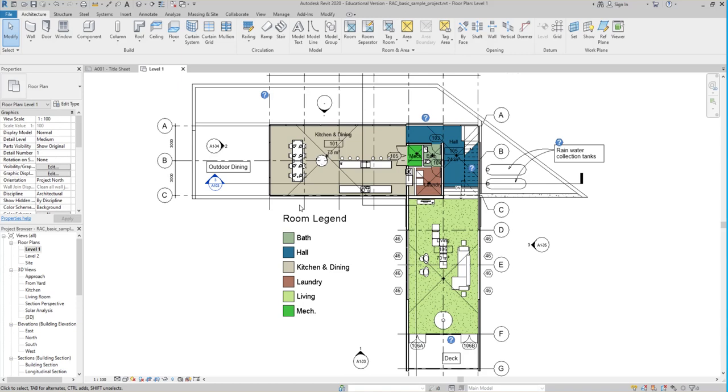If you're thinking in terms of engineering, line weights a lot of times, like if you're a mechanical engineer, and I mean that like nuts and bolts, right? You're doing product specification. Line weights are going to be associated with things like what you cut. So if you're working with a laser cutter, magenta means score the item, and cyan means cut, right? So if you're cutting out a piece of plexiglass, cyan would mean cut it, and magenta would mean score it, like put a pattern on it, okay? So that's what line weights are going to be used for in engineering, all right?